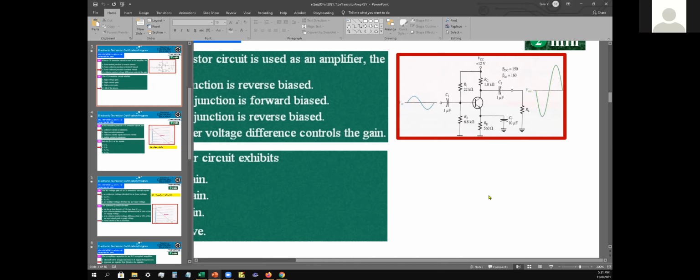Right. So the confusion would be that, regardless of how the schematic looks, it seems like DC is going right and DC is going left. DC doesn't have oscillation. Yeah, DC would get blocked right here at C1 as well as at C3. Right. So that's why the DC only operates by turning the transistor on or off. That's it. Right. All right. Thank you.